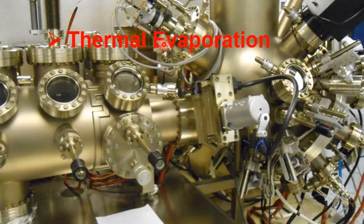But dear student, please note that there is a possibility of impurities from the substrate due to the higher temperature inside the reaction chamber of thermal evaporation, and there is also a possibility of collision inside the reaction chamber. So due to this, we cannot guarantee that the film deposited with thermal evaporation will be highly pure or comparable to molecular beam epitaxy, though this technique is advantageous over molecular beam epitaxy in terms of cost, because the vacuum used in thermal evaporation is low, and it's not ultra high like molecular beam epitaxy.